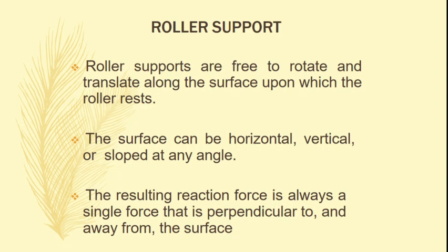The surface can be horizontal, vertical, or sloped at any angle, whatever it may be. The resulting reaction force is always a single force that is perpendicular to and away from the surface, because in the perpendicular direction the beam cannot translate. It translates along the surface, not along the perpendicular direction. That is why the translation is restricted in the perpendicular direction, and that is why we get the reaction force in that direction only.